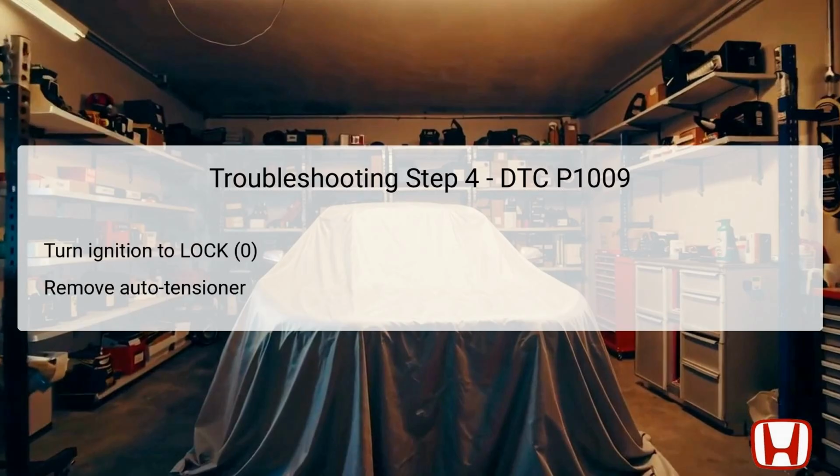In this step, you should turn the ignition switch to the lock position, also known as position 0. This action is necessary to ensure that the vehicle's electrical systems are completely powered down before attempting any mechanical repairs. Following this, remove the auto tensioner from the engine.